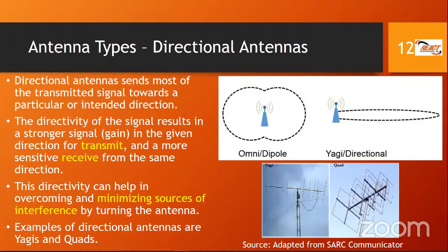Excellent question there, Jermaine. So what I may have neglected to mention is that when it's up in the sky and you're sloping the elements, that is usually for VHF, UHF bands. One will hardly ever put a VHF, UHF antenna on the ground per se. So normally the on-the-ground antennas we're talking about are really HF antennas, where the lengths are much, much longer. For the shorter antennas, and also because of how radio frequency propagates for VHF and UHF, you really want height. Height is might when it comes to those frequencies.